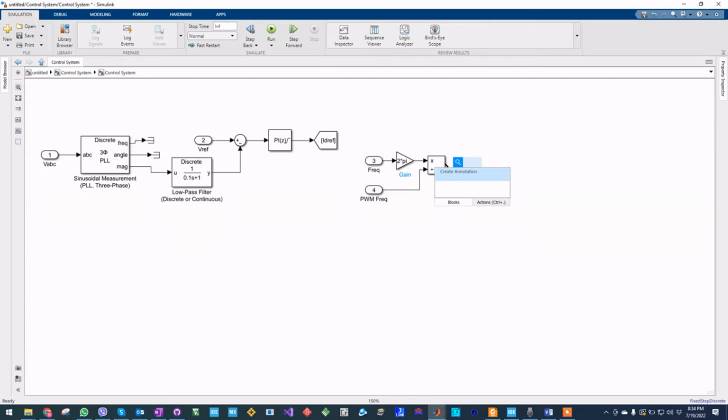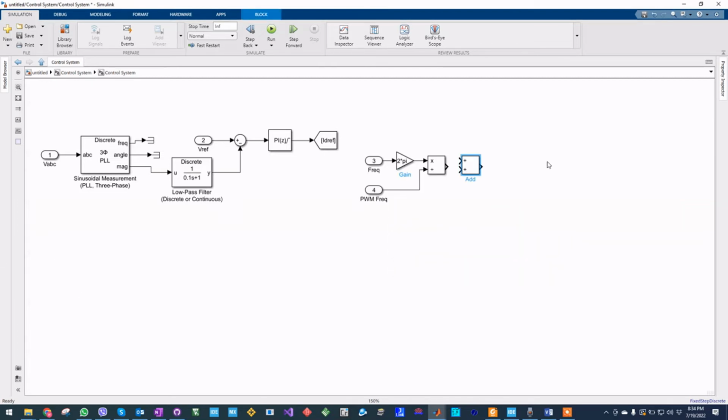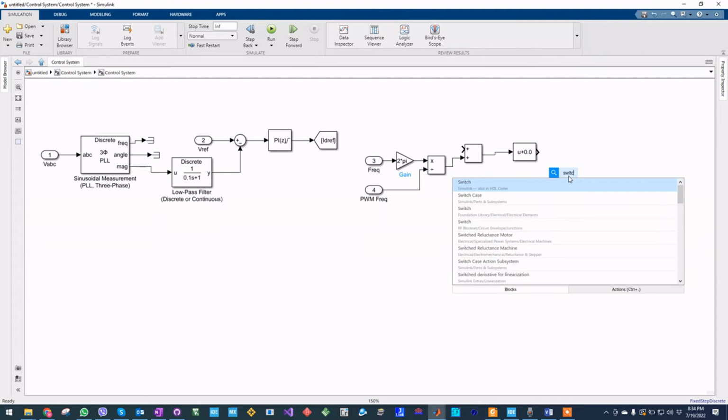So for now we will try to get the absolute theta. For this we will add the step size to the previous value of theta. So we leave the previous value of theta for now as it is. We add a bias because we want to roll over this frequency; this theta should be between 0 and 2 pi. So whenever this theta is above 2 pi, we want to switch it back, subtract 2 pi, so that it is always between 0 and 2 pi.